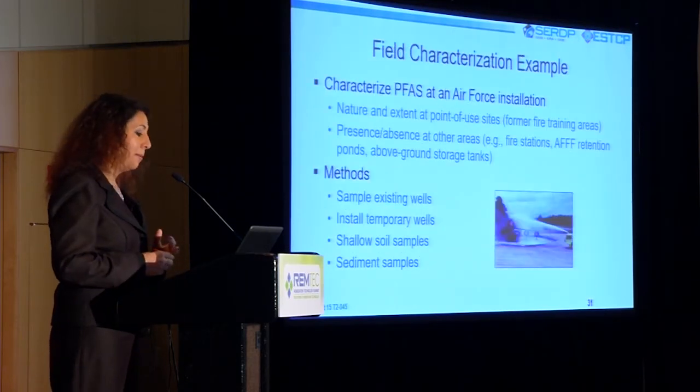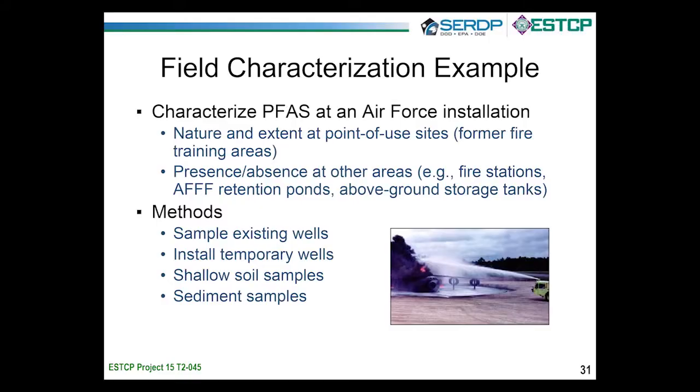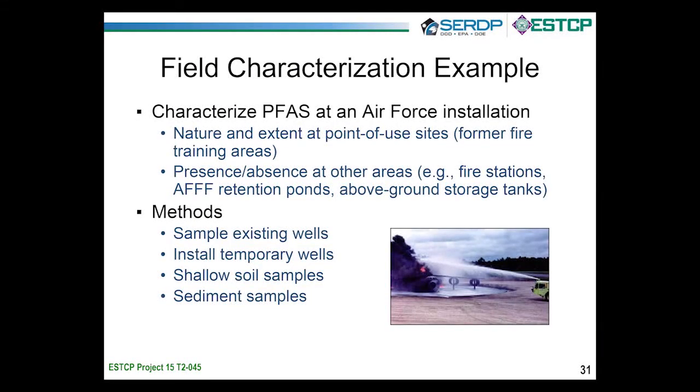I'm going to talk a little bit about a field characterization example. This is some of the early work that was done on behalf of the Air Force as they were trying to develop their sampling programs at a lot of their installations. So the first 3 projects that were funded by the Air Force, two of them were led by me, and the scope of work was to define the nature and extent of contamination at point-of-use areas like fire training areas, but also to get a yes-no answer on where PFASs may be present at some of these sites, including fire stations, AFFF retention ponds, and above-ground storage tanks.